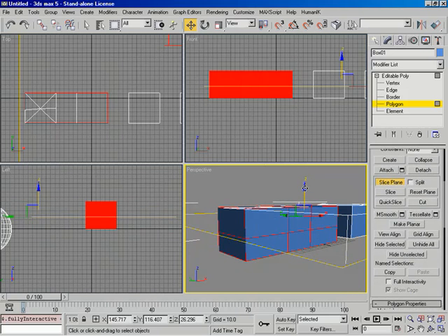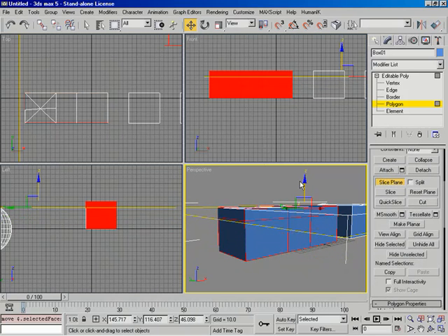If I was to turn it off and now come back over here and I slide my slice plane up and down, look what's happening. It only changes after you let go of the mouse. It doesn't actually track each motion of your mouse. Exactly. Very cool. So I'll turn full interactivity back on, and now away we go.